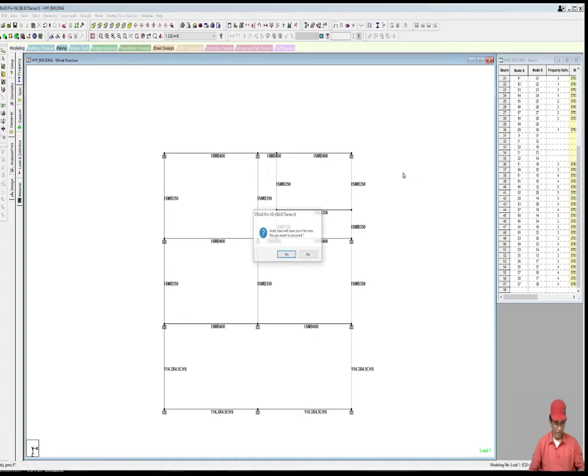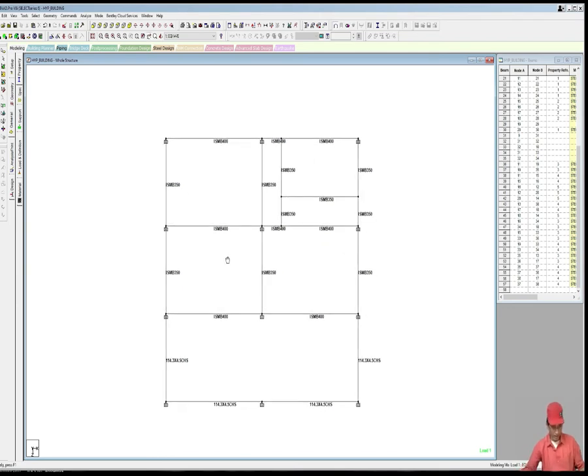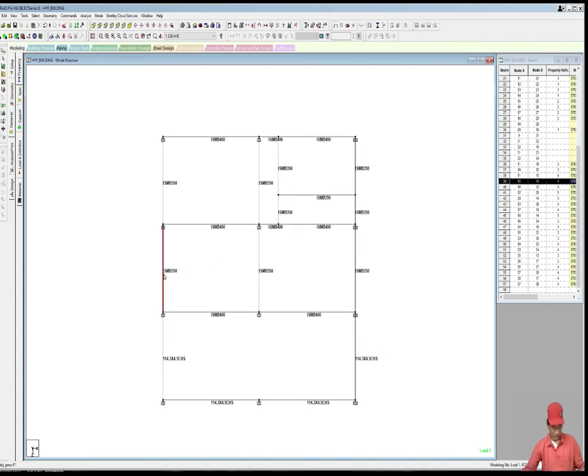So basically the I columns will be oriented such that these members will have to be connected from the web. So making moment connection at the web is a bit difficult. So generally in design practice, we provide cleat connection from the web for any member protruding out of the column from a web.